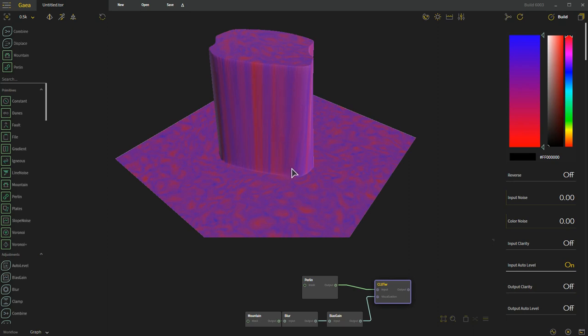So you could go ahead and take this into something like Maya or ZBrush, and you could rebuild the topology in here so that it would actually have more potential for detail, which you could then sculpt in, say, Mudbox, ZBrush, Blender, any one of those tools directly in Maya as well. Once you'd sculpted that detail in there, of course, UVs, as I mentioned, and then any texturing that you had done initially inside of Gaea that you want to transfer over to make use of, you can bake that information.